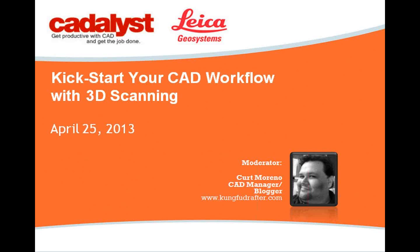Well, okay. Now, can you clarify exactly what you mean by terrestrial scanning? Yeah, there are several types of scanners available, and one of the most common uses that has been around for a while is airborne laser scanning, where they fly over a large area and capture huge swaths of land with what's called a LiDAR laser. Our scanners have been LiDAR. The first laser scanner made by our company back in '96 was a terrestrial scanner that sits on the ground. It's stationary. It's used very similarly to a total station, and it's made to collect data from the ground.